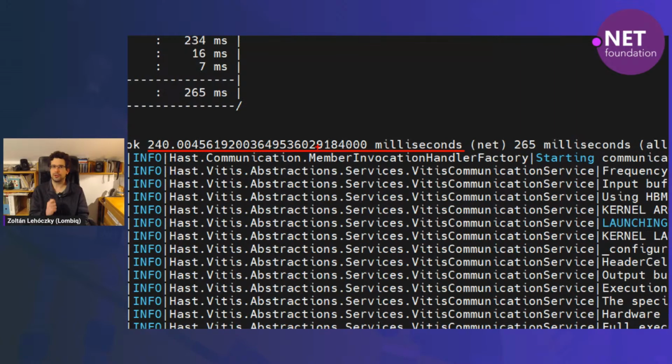That's actually one of the advantages of using such hardware execution, is that your execution time is reliably exactly the same. Well, if you compute the same thing, so with the same inputs, it will take the same amount of time. And again, this is because on the FPGA, nothing else is running. It's just your logic hardwired into the hardware. There's no other software running there. There's no software running there at all. It's just pure bare metal.